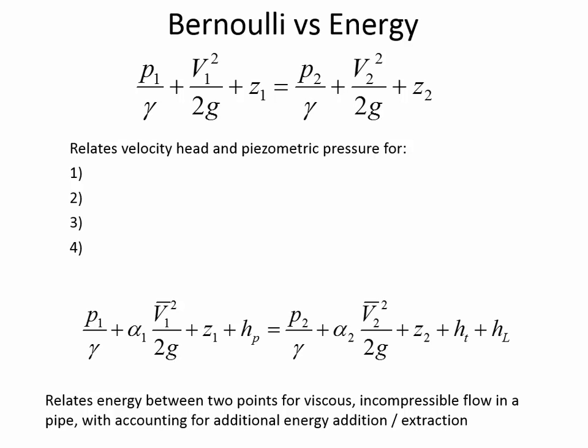And sometimes local losses are pejoratively referred to as minor losses. But you're going to give local losses a Napoleon complex if you call them minor losses. Make them think that they don't matter. They're called minor losses because in comparison to frictional losses, usually local losses are much smaller.